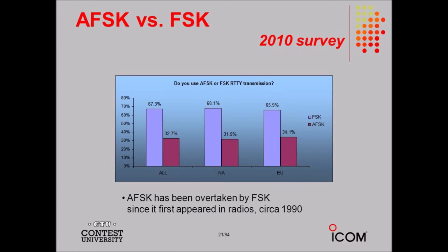Okay, page 434. Continuing the reading. Figure 25.3 shows a spectral display of an AM voice radio signal. The horizontal scale is calibrated in increments of 1 kHz per division. Each vertical division represents 3 decibels of change in signal strength.